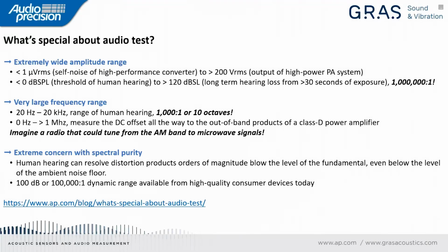In terms of just human hearing, the threshold of hearing is generally thought to be around 0 dBSPL, and humans can withstand 120 dBSPL or even as much as 140 dBSPL. Of course, there'll be some hearing loss at that upper range, but really even just within the range of human hearing, we're talking about a range of more than 1,000,000 to 1. So it's really this very, very large amplitude range, and we can't statically compensate for it. On an oscilloscope, you might change from a 10x probe to a 1x probe, but here we're talking about a continuous AC signal, and that dynamic range could change instantaneously.